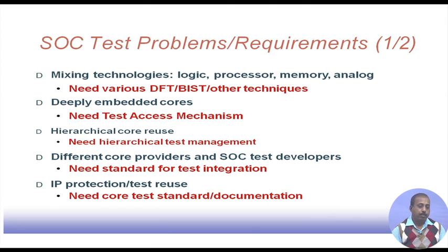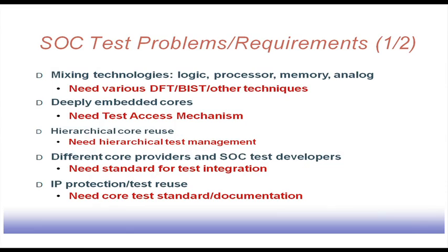Secondly, generation of test patterns is difficult, because I do not have the full detail of all these components. So, I cannot design an ATPG process so that test patterns can be generated for the processor, until and unless I have got the gate level netlist of the processor. So, naturally, that stops an integrator from designing the test vectors or test technique for a particular component of this board, of this chip.